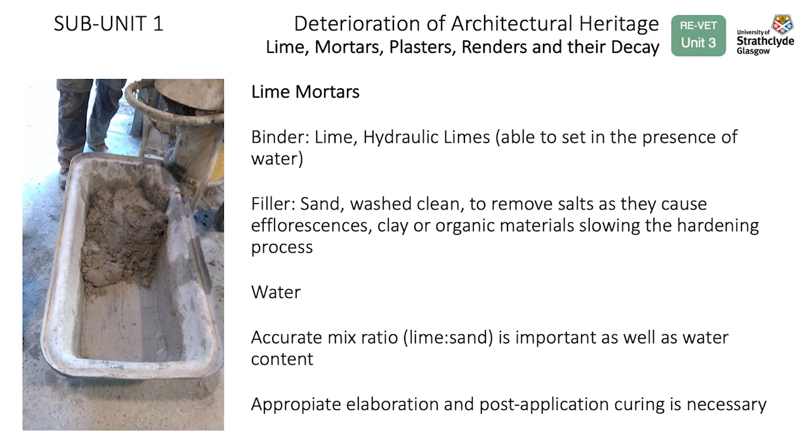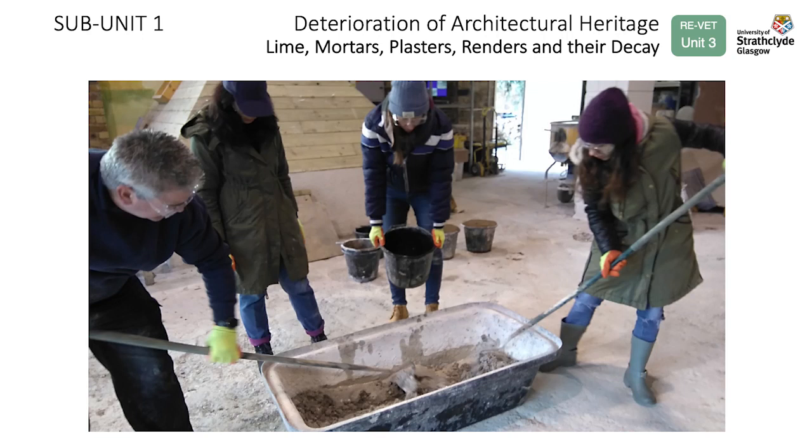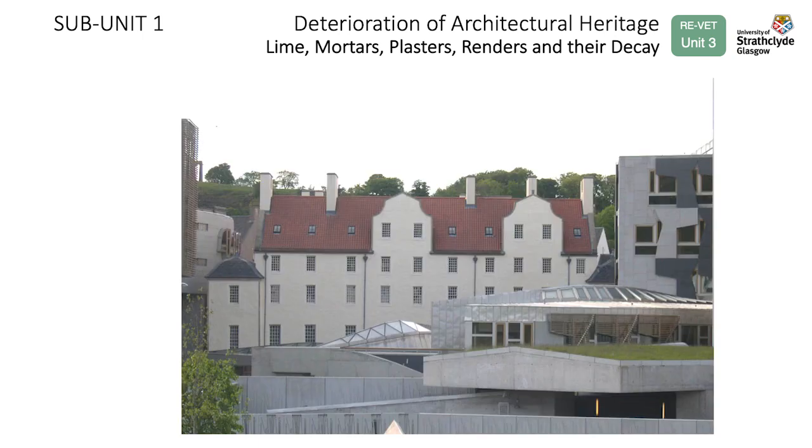Lime mortars are composed of binders, lime or hydraulic lime, which are able to set in the presence of water. The fillers are sand, which should be washed clean to remove salts as they cause efflorescences, and clay or organic material slowing the hardening process. Water is also an important component, and there should be an accurate mix ratio of lime and sand as well as water content. It is also necessary to have appropriate elaboration and post-application curing.